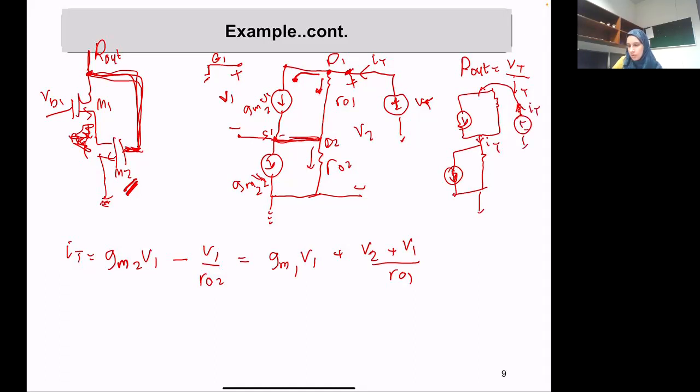Okay. So you can do this simplification, it's going to take some time, then I can explain it again. But what at the end, we get GM2. All of this is just replaced by 1 over GM2. So it's quite surprising that this entire impedance is just 1 over GM2. I mean, you need to use your KCL tricks.